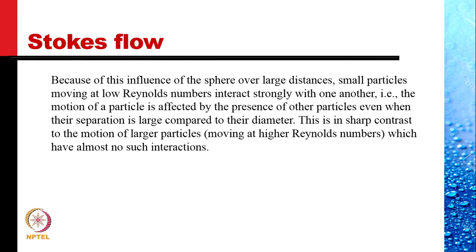Because of this influence of the sphere over large distances, small particles moving at low Reynolds number interact strongly with one another. That is, the motion of a particle is affected by the presence of other particles, even when the separation is large compared to their diameters. This too is in sharp contrast to the motion of larger particles, which have almost no such interaction.